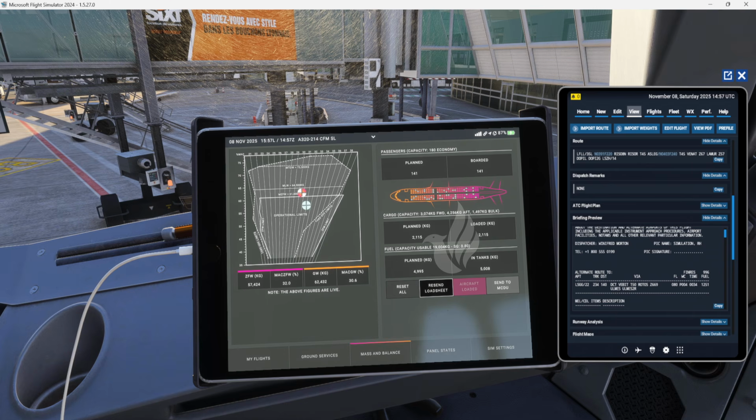In general aviation aircraft it is the same thing, but there you have a speed that we call VA, which is the maneuvering speed. If you pass the maneuvering speed, for example in the Tecnam 2002, where the maneuvering speed is 101 knots, you should be careful on the controls to not get structural damage. So this is about the zero fuel mass.